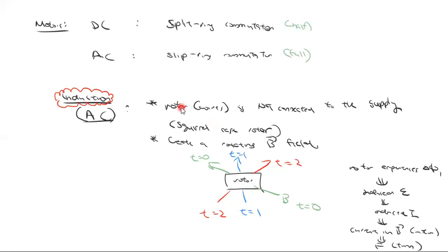And so how is the induction motor different to the motors that use these? Well, with these, your rotor is a wire that is connected to the power. You literally directly pump current through those wires. Whereas for an induction motor, this rotor has wires, but it's not connected to anything. And how you get it to turn is you create a changing magnetic field, which in simple terms is using AC. We won't get too much into detail on that, but you have coils placed around it and you basically pass current through them at different times. And the end result is the magnetic field is rotating, right?